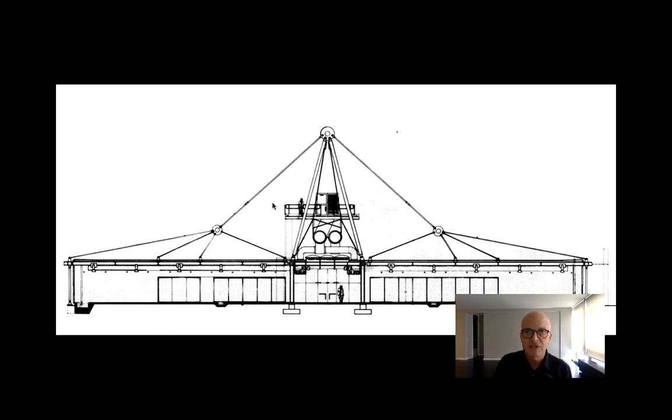And you can see that they're attached to these steel discs. And here, for example, we have 1, 2, 3, 4 steel cables that are holding up the Patscenter's roof on this side. And the resultant of those 1, 2, 3, 4 cables is actually a line that is that direction and that sense, right, going down right to left. The internal stress that the big cable is providing to resist that is equal and opposite to the resultant. So it is being pulled up this way. And if you do the math, if you add up the forces in each of these 4 cables, put them head to tail, what you get is a resultant that looks exactly like this, right?